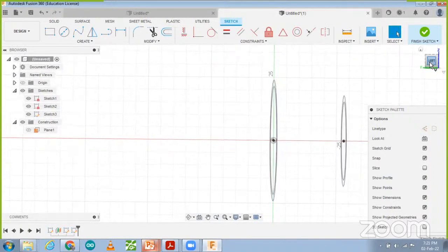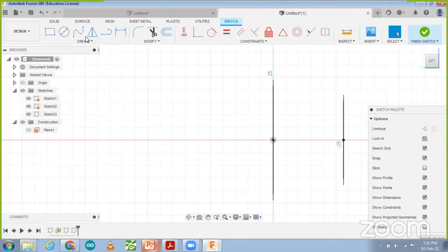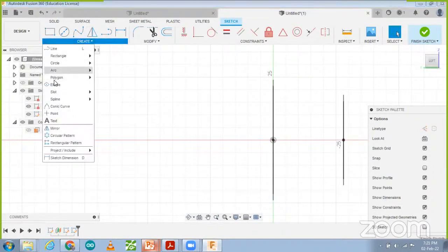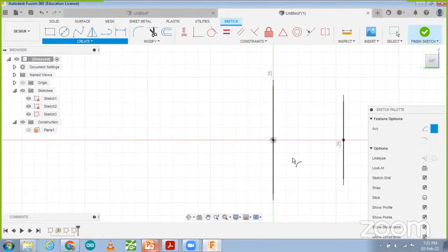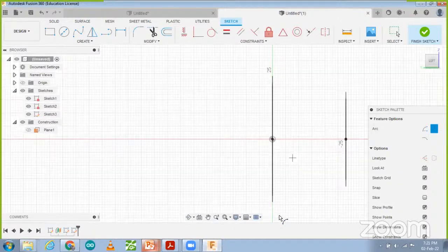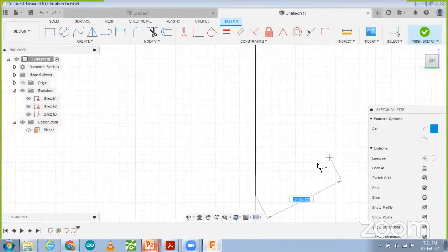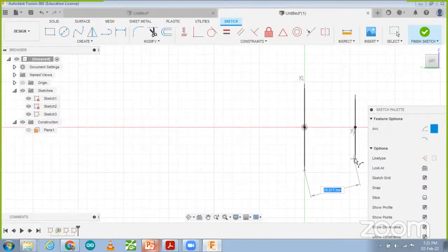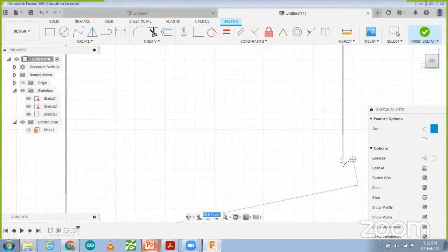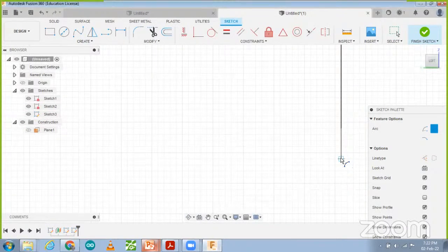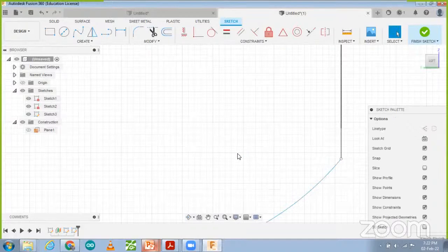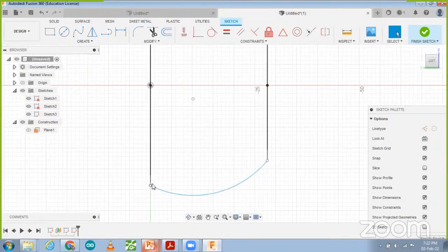So left, and over there we have to make one line or arc, 3-point arc. So 3-point arc we are going to make it over here. So this point should be selected over here, 1 point, and then after that second point we have to make it over here. On this face, then we are going to make it like this. So this one arc we have selected it, but constraint we are not able to select it over here. That is the major issue that is occurring.